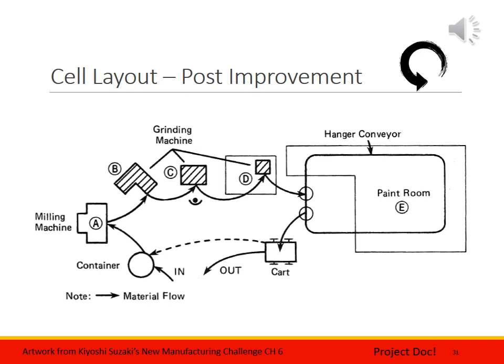If I'm stuck with heavy automation, there's nothing I can do about it. I've got to have 2 people there. It doesn't matter, because 25 parts got to go in, 25 parts got to go out. But if it's one-piece flow, I can fly in this cell. I can dial it back with 1 operator, or I can absolutely fly with 5. And what that means is no overtime. I flex my manpower, I run it on a day shift, I run it for 8 hours, and everyone's going home at night to see Mama and Papa. That's the way you want to run a cell, a cellular environment.